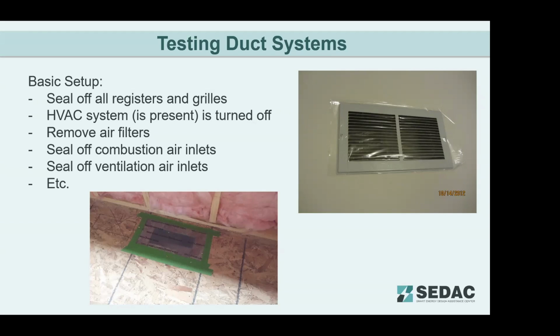I will say on the subfloor testing, the trick to one of the hardest obstacles, I guess, is that the tape doesn't always like to adhere to the subfloor, particularly if there's dust on it. It can kind of peel up. So sometimes you can see 2 different types of tape being used to get a little better seal. But I've also seen foam gaskets and whatnot.